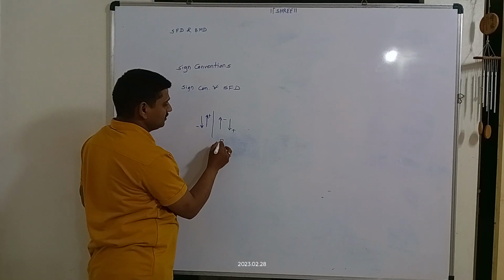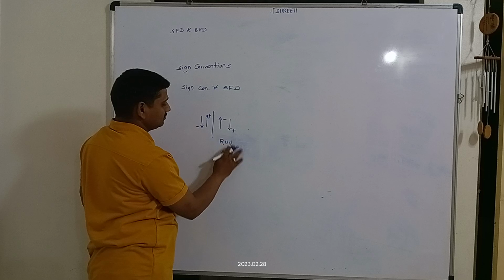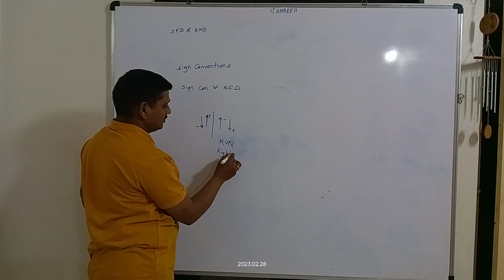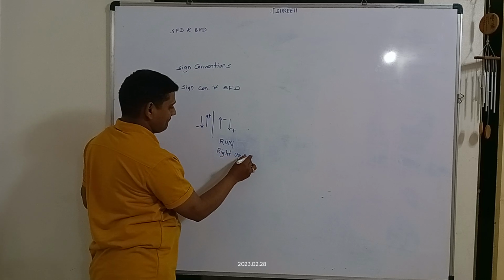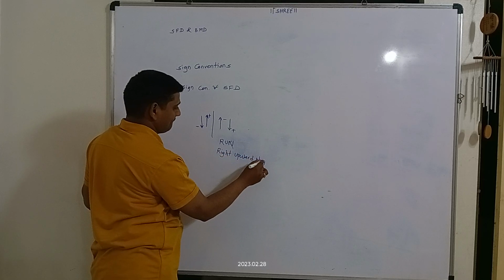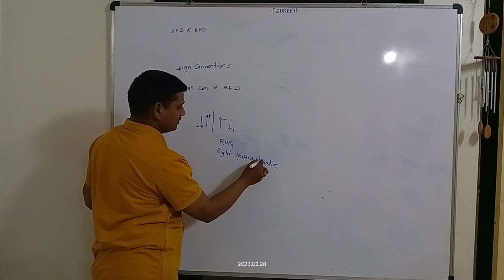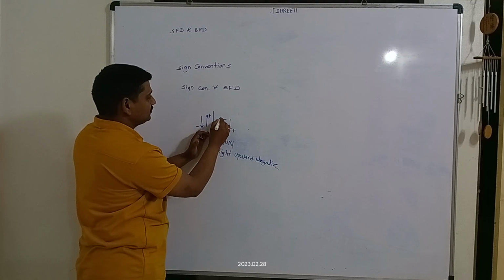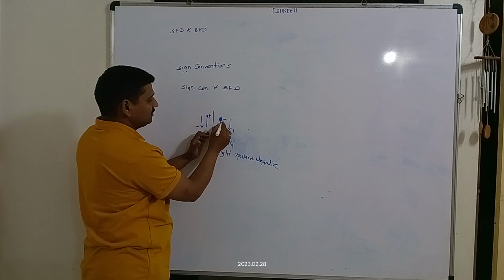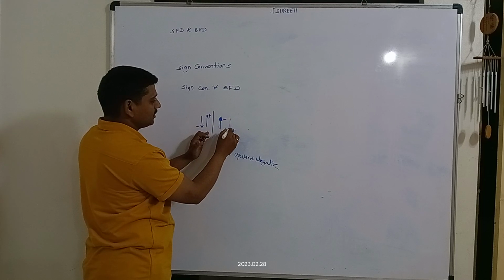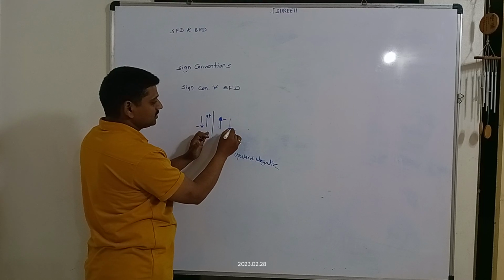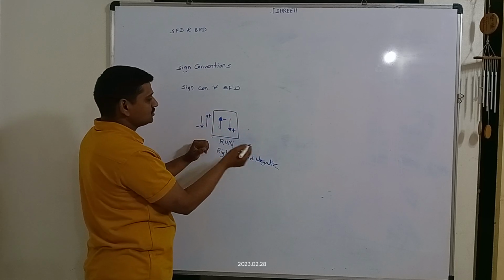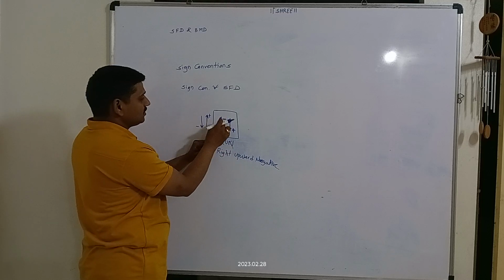We can say RUN, means right upward negative. That means to the right of the section, the forces which are going towards the upper side are negative, and opposite to that, the forces going towards down are positive. Only this we can remember for further processing, and the sign convention for the other side is opposite to this.